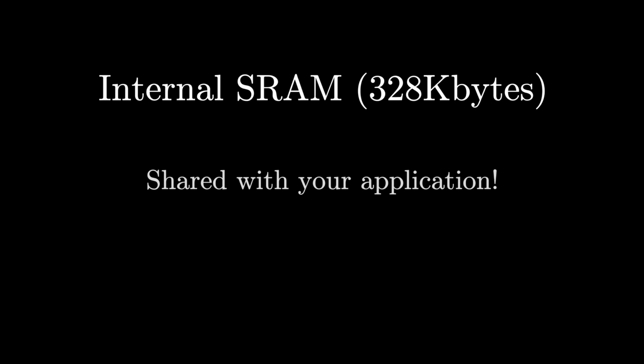There is also a limitation that DMA buffers cannot be allocated in PSRAM, so we are limited to the internal SRAM of the chips. This limits us to a maximum of 328K. In testing with my walkie-talkie application, I managed to allocate a total of around 100K before the application started to run out of memory and crash.